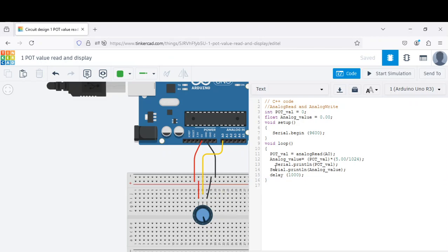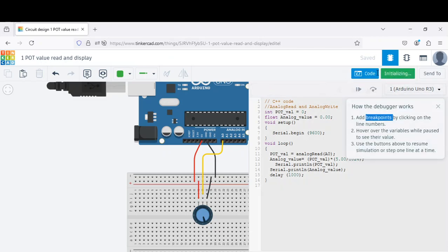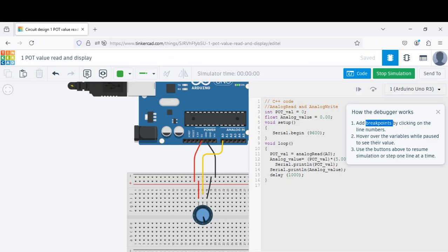So there is an A to D converter. This pot value is going to hold the decimal equivalent of this digitized analog number, and that is now converted to the analog voltage. Pot value multiplied by this is the conversion from the decimal to the analog value. So this is what's happening here. Now I can run the program. We will just see in detail what happens.